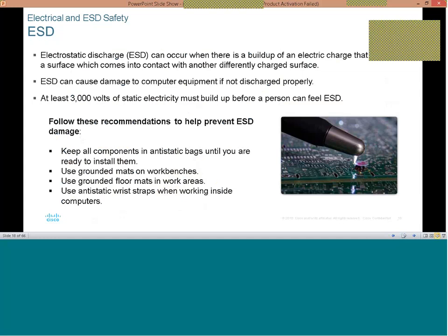So it is best that you use what we call a strap, more or less, when you're doing the troubleshooting. The reason is just to be able to earth those trapped ESD, that's the electrostatic discharge, to discharge all that static electricity from your body down to the earth, so you can earth it down to zero.